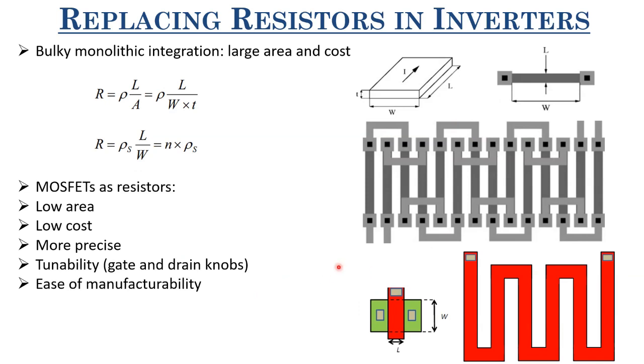Now also, if we have to fabricate only memories or only transistors on a chip, then it's easier during manufacturing. Because all these different components, when we want to realize them, require different masks. So if you have different components on a chip, for instance MOSFETs, resistances, and some capacitance implementation, then basically we require different masks.